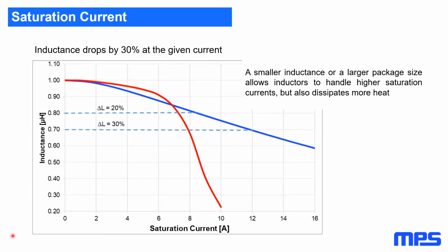So the self-resonance frequency is strongly depending on the relative permeability of the core material. The higher the permeability, the lower the SRF. Air coils without a ferromagnetic core show the highest self-resonance frequency. Therefore, they are perfect for high frequency applications. When designing a DC-DC stage, please keep in mind to use an inductor with a much higher SRF than your switching frequency.